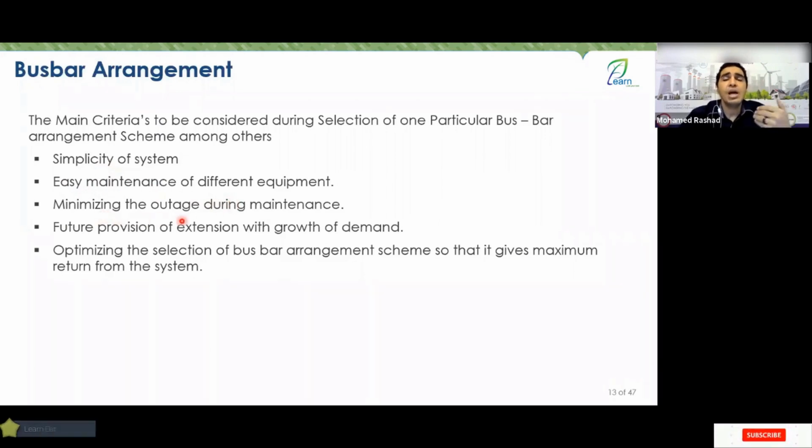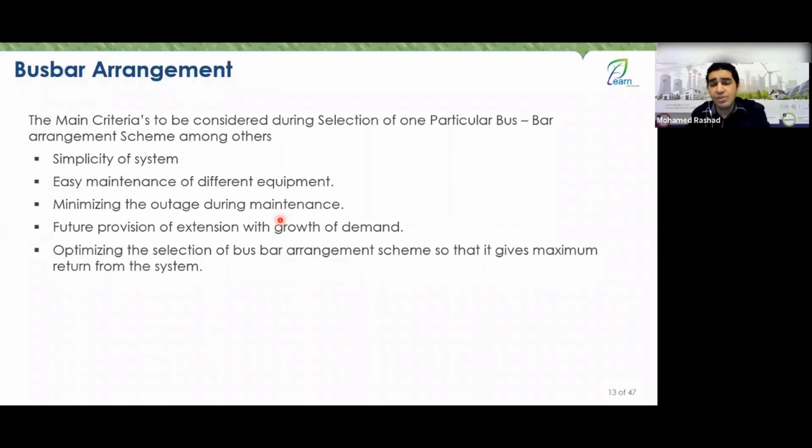This distinguishes the outgoing gear from the incoming, like the example I'm telling you about now. If one of them fails and you need to perform maintenance, if you come to maintain this socket, all the other sockets are connected from the same connection. If you come to this socket and want to connect or do something, you might get electrocuted. So you're forced to disconnect the supply from all of them. Therefore, you need to think of a way to minimize the outage during maintenance, meaning you reduce the disconnection of other loads during maintenance operations.